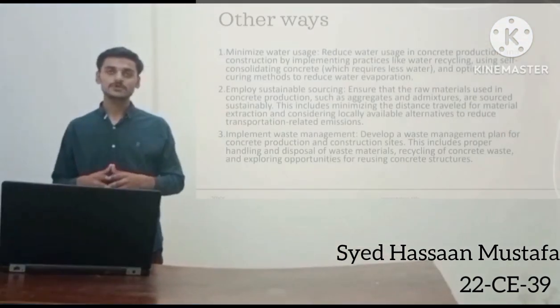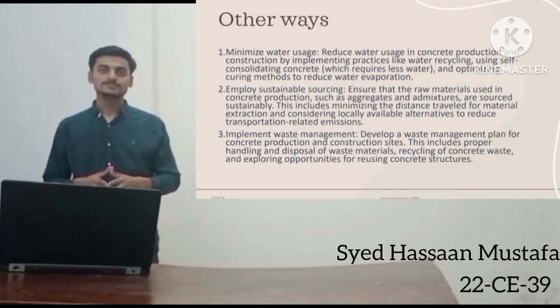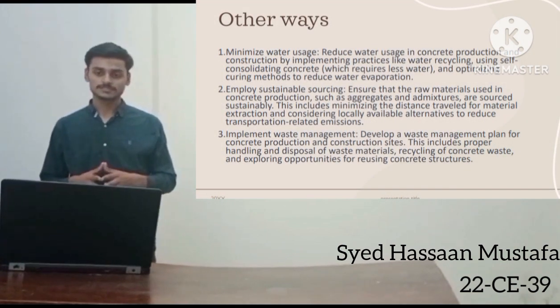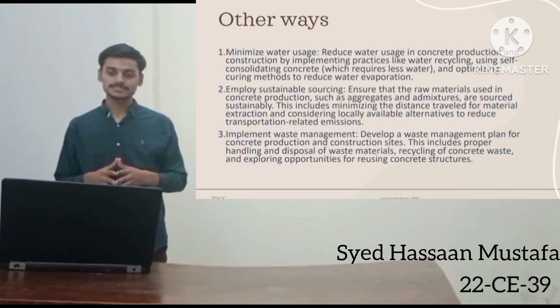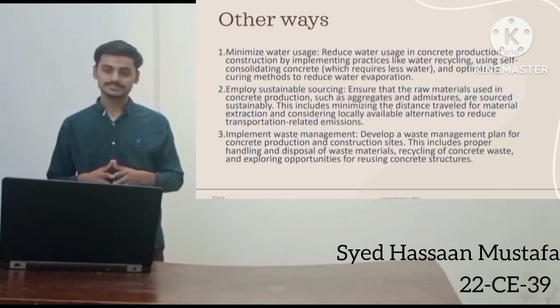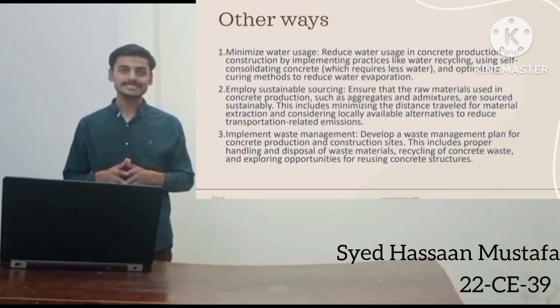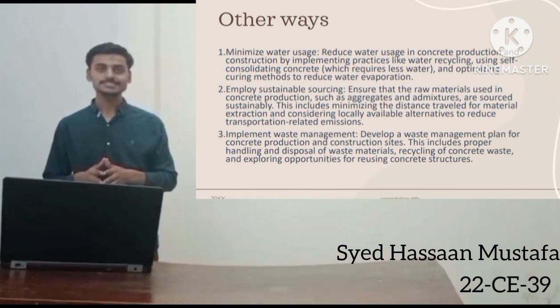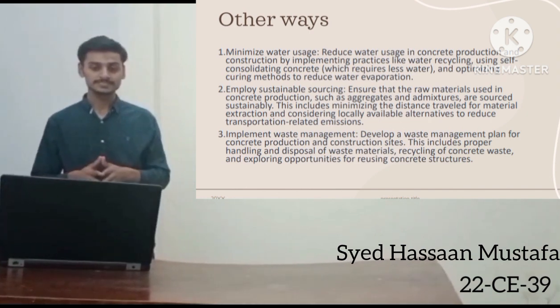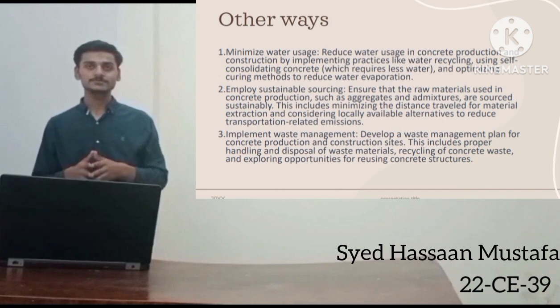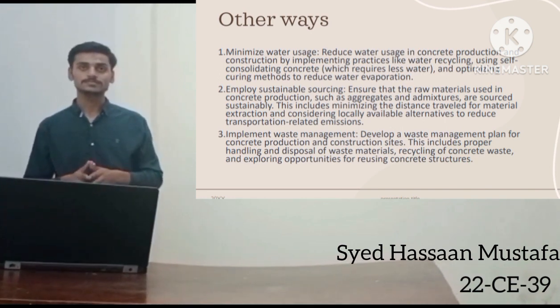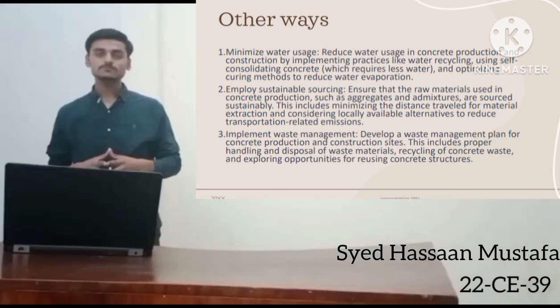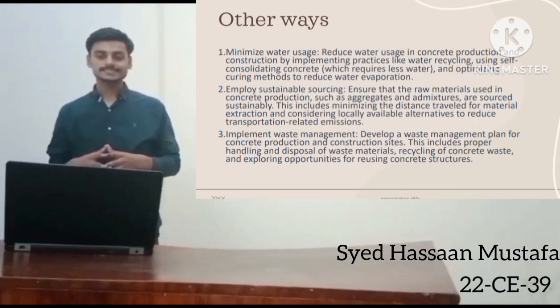Another practice that must be adopted at the construction site is the reduction of water. More use of water is also a defect of concrete. We should reduce the use of water at construction sites by using self-consolidating concrete and optimizing curing methods to reduce water evaporation.